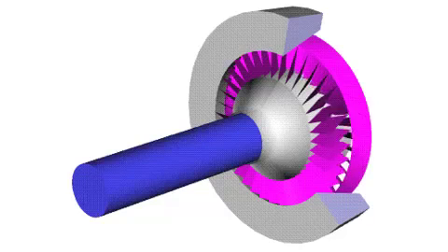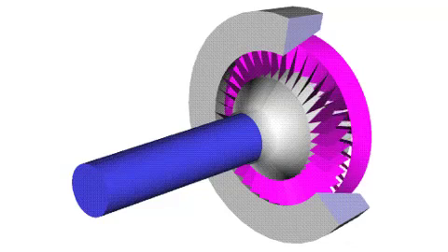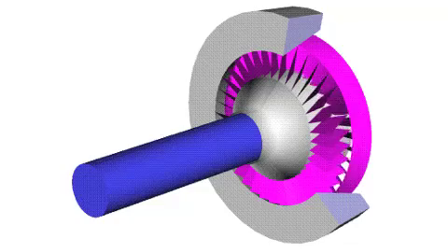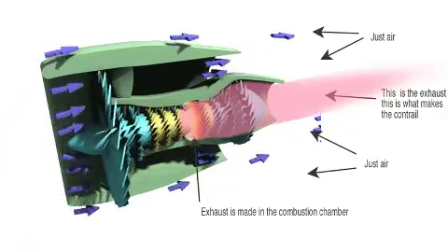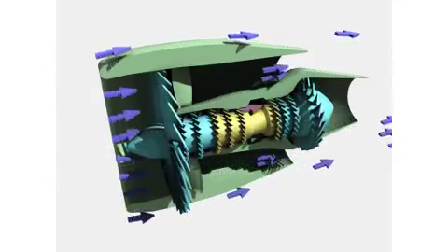Turbine. The high-energy airflow coming out of the combustor goes into the turbine, causing the turbine blades to rotate. The turbines are linked by a shaft to turn the blades in the compressor and to spin the intake fan at the front. This rotation takes some energy from the high-energy flow that is used to drive the fan and the compressor. The gases produced in the combustion chamber move through the turbine and spin its blades.